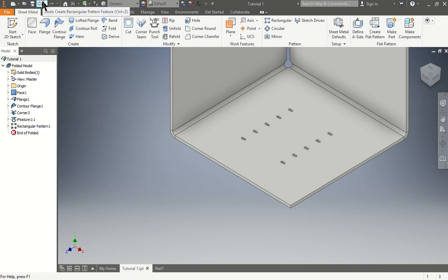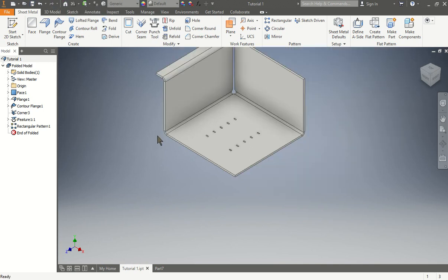And let's continue. Now that we've done this, we're going to add another bend feature to the other side. For the bend feature, we're going to create a plane to the front face of the flange. How should we do a plane? We're going to do sketch, right? And which is the plane we're going to use? Wrong. We should go make our plane over here.